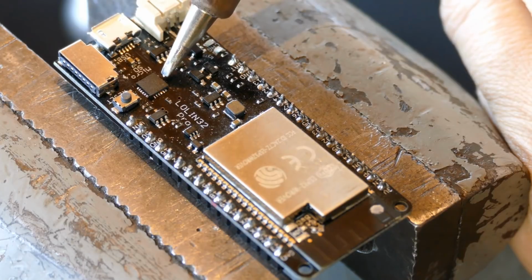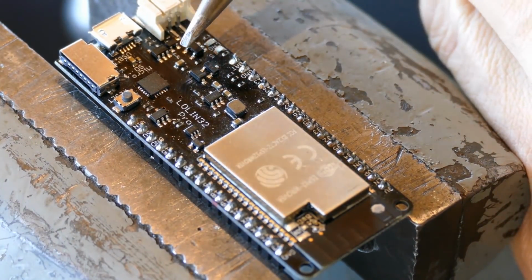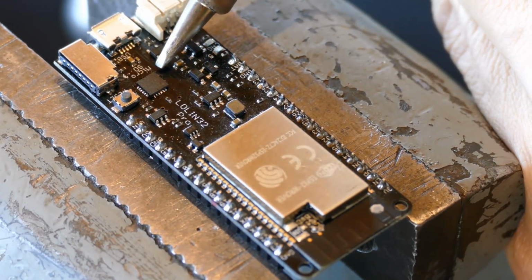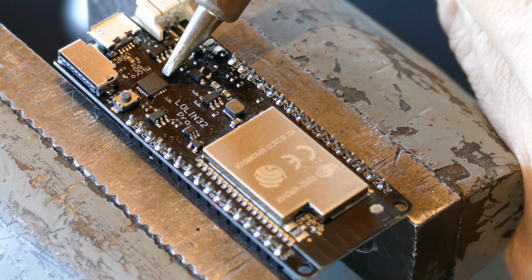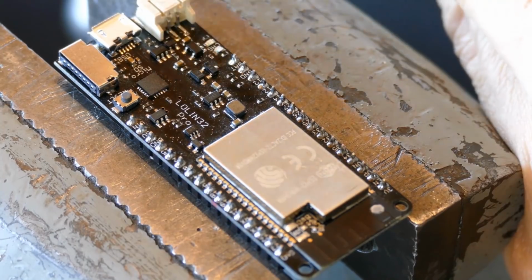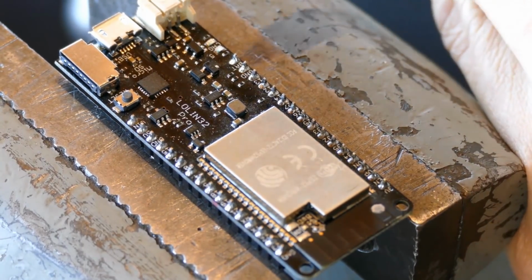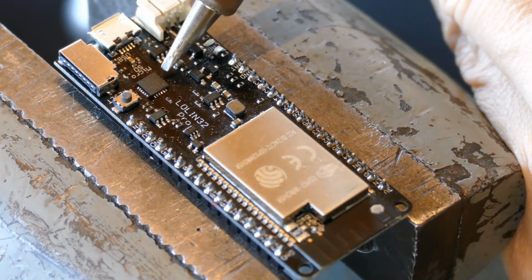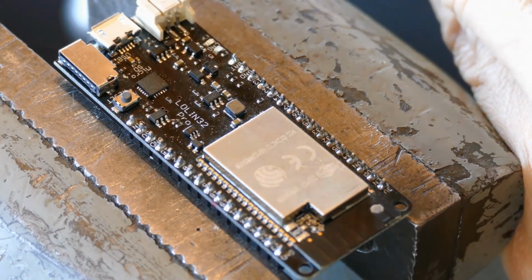I turn the chip around in the vise to get better access to the two sides with solder bridges. Sorry about the camera angle. I'm just carefully brushing my iron over the bridge pins to scoop up the excess solder, cleaning the tip between brushes. Despite my sloppy reflow, all the pins look okay. Another cleaning, and it should be ready to test.